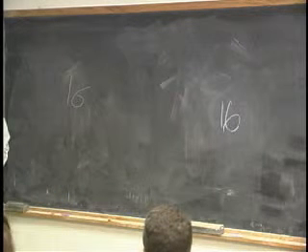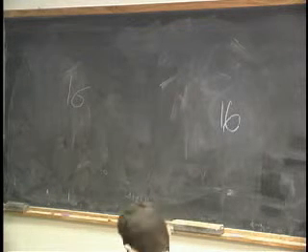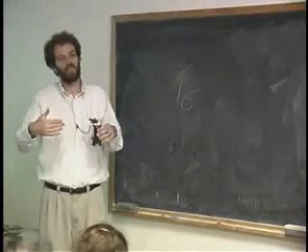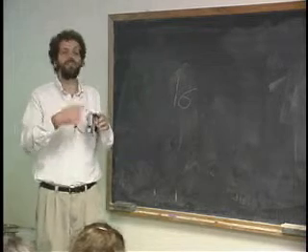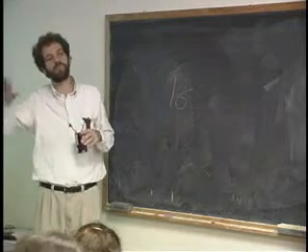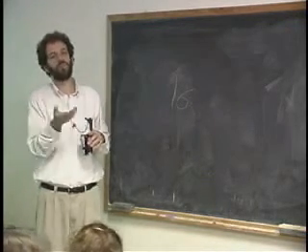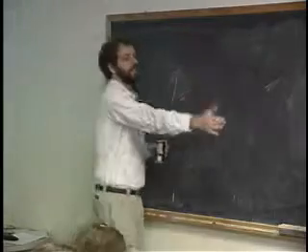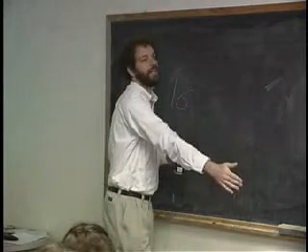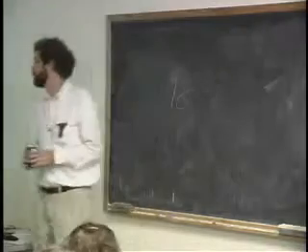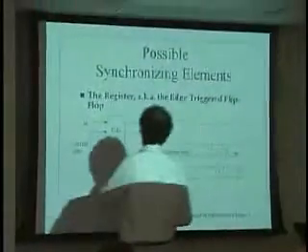But you understand what just happened here. Without a synchronizing delay, without me saying wait, okay, now do it, and then wait, okay, now do it, this system gets out of control and it races ahead, and different parts of it go faster and different parts of it go slower. It's very difficult to control the speed of the feedback so that all parts of the feedback operate at the same time. And so the key is delay. We put a gate there, we say don't do it yet, okay, now go, and then you close the gate. And then you wait, okay, go, close the gate. And that's why you need that element down in the bottom to synchronize the delay. So effectively, we're going to talk about why we need a register here.